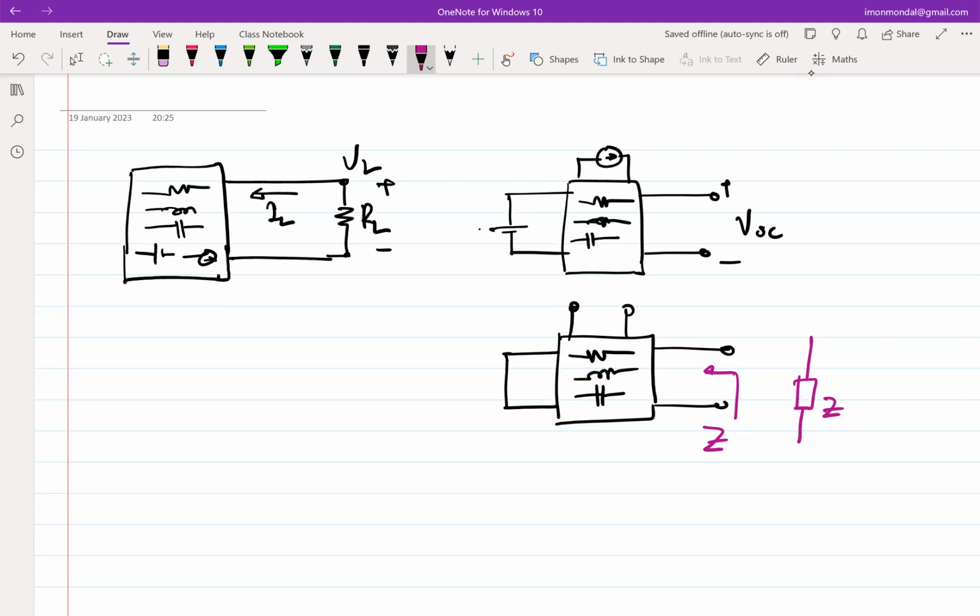He said you can put a multimeter. Experimentally, yes. Right? So essentially, a multimeter does this for you. It has an internal voltage source. You put a voltage source and you figure out what the current is, do the division and show you a number. We are doing this for a particular frequency. In a multimeter, it will show you a number for a specific point, but it need not be for a particular frequency. When you do the calculation, this Z can be Z of omega, right? It can have a frequency dependent component.